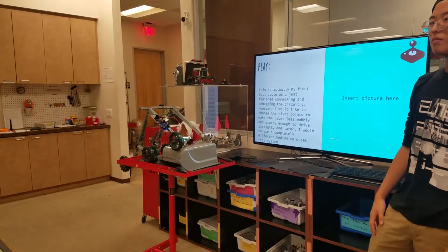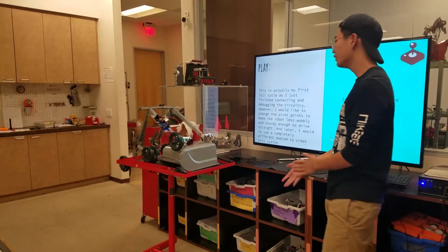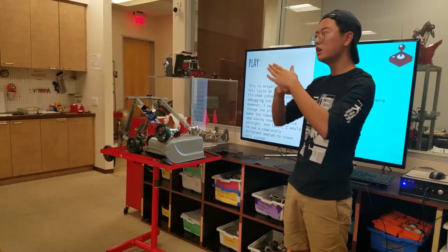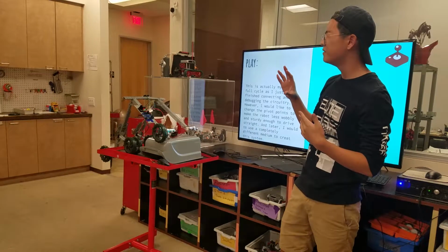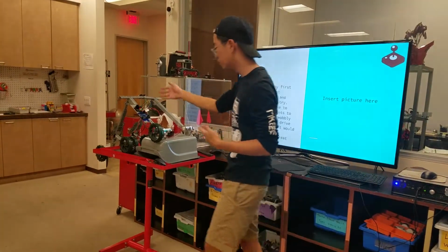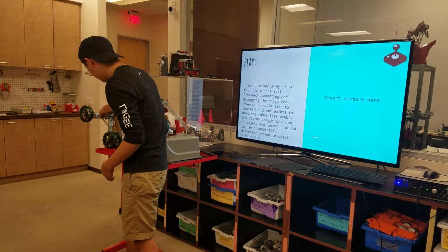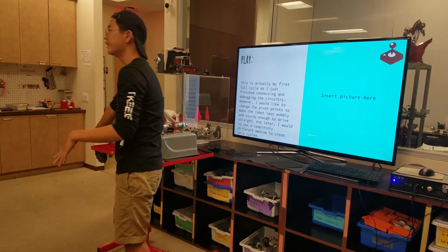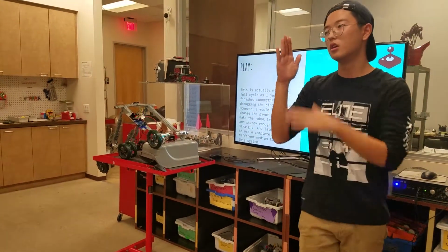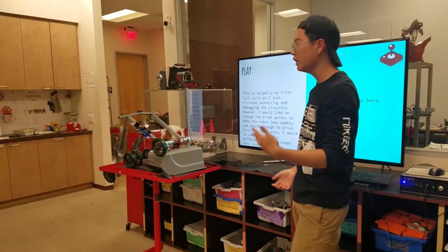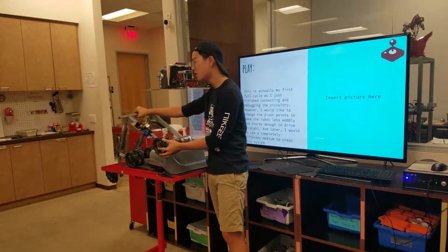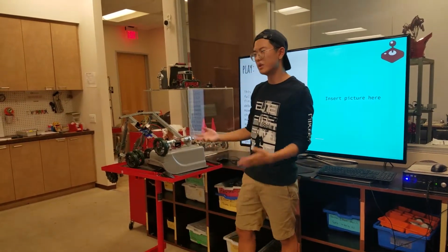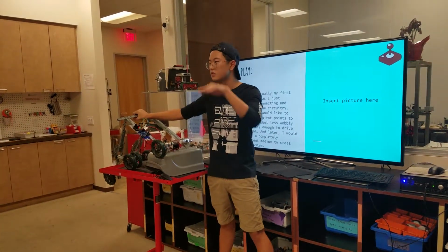I'm just having a little bit of trouble seeing. How does that replace a suspension system? Okay, so basically it has a tolerance rate of 45 degrees. So any object at 45 degrees and 80 to 60% of its maximum height here, just right here. As you can see, I think that's around 16 inches the last time I measured. So it should tolerate around 10 inches of obstacles at 90 degrees. So it technically should be able to drive right over it, and this hinge right here should stay level to the ground, or as close to level so it won't move as much, which is basically what a suspension system does. It carries the load at the same place without turning.